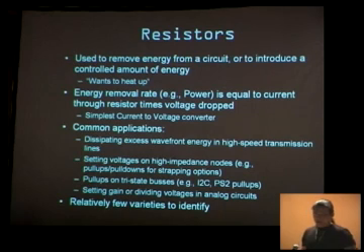The common applications in modern motherboards are typically to dissipate the excess wavefront energy in a high-speed transmission line. Just like my sound waves are echoing off the wall because the walls have a very high impedance and reflect, a resistor would be like putting foam padding on the wall, so the waves going through the copper wires actually hit their destination and don't bounce back. That's typically what you see them for.